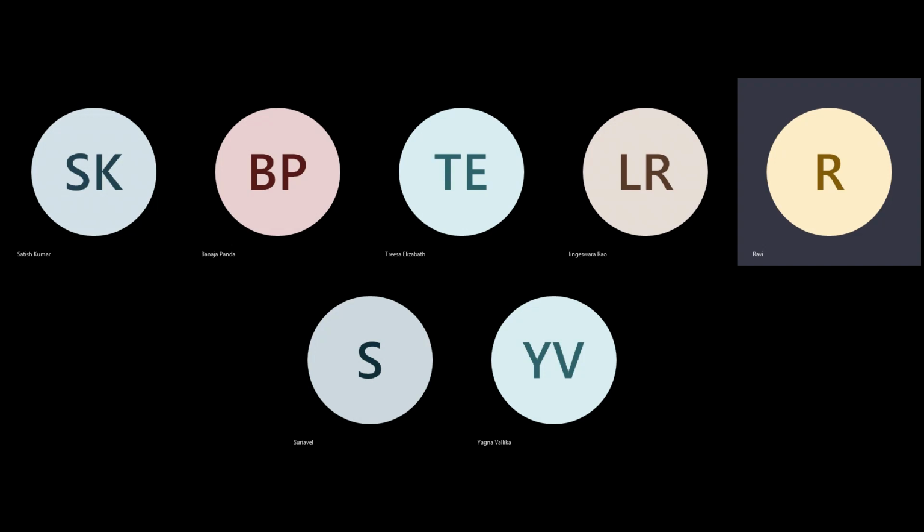Then what happens is your access time will become more, so it at least needs one buffer. If each macro width is, let's say, 80 micron, plus some routing, say a 10 micron gap I'm leaving, so 90 micron.